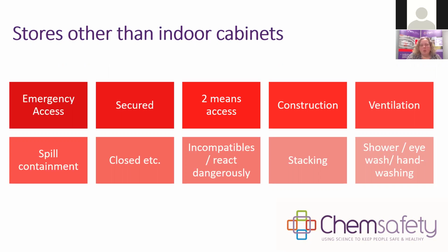And we need to make sure that our substances are kept away from things that are incompatible or react dangerously. Make sure that we're not prone to stack collapse with how we stack substances, and making sure that there is a safety shower, an eye wash and hand washing facilities available. But if they're stored in closed packages, then just hand washing facilities are required.